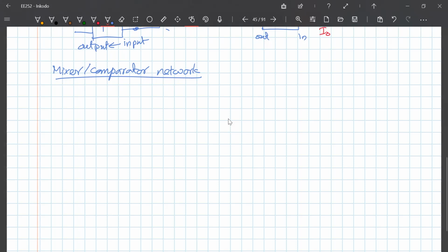Where beta is just a number because input is a voltage and output is a voltage. But on the other hand, if my input to the whole circuit is a current source, then I cannot subtract a voltage from a current source, right? So in that case, I need to have a current as the output of the feedback network. So If should be the output of the beta network. Though the input to the beta network, the feedback network, is V out, a voltage, the output has to be a current If. So therefore, If should be equal to beta times V out, meaning that my beta has units now.